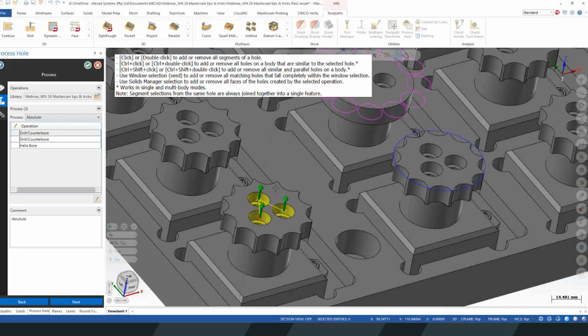Now what I've noted is, when you programmed your files in the other file of Mastercam, your plane reference must be all set to incremental when you want to apply these settings. So currently you can see I've got two Toolpath groups in that file. I've named them absolute and incremental. These names will be according to what you name your Toolpath groups. So I did testing. As you can see, absolute would give us issues. It wouldn't bring the Toolpath in correctly, but if you use the incremental version of it, it will.